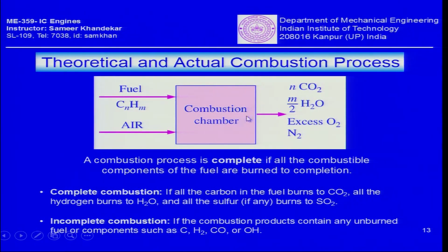That means the exhaust which came out of the combustion chamber was not completely oxidized products, but also contained some unburnt elements or unburnt molecules, which can still oxidize. If they oxidize outside the combustion chamber, whatever energy is released, which may lead to complete combustion outside, that energy will be lost as far as this combustion chamber is concerned, because we are extracting the heat only from here.